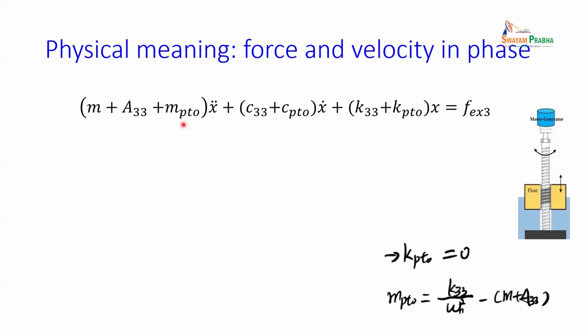We still write the equation here, right? Mass, damping, stiffness, excitation force. And if everything is harmonic, right? Everything is harmonic. x equals capital X times e^(jωt), right? We write everything in the force, right? And this jω time. Let me say it that way.